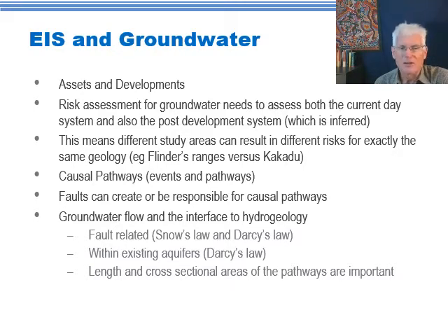Then it's important for us to just mention briefly that groundwater flow and the interface between, say, structural geology or traditional geology and hydrogeology, particularly for faults, needs to consider fault-related flow that's governed by either Snow's law or Darcy's law. So Darcy's law covers flow through a continuous medium like a porous sandstone. Snow's law covers flow along fractures, and that's important particularly for fault damage zones. And then there's also flow within existing aquifers, so that's typically Darcy's law.